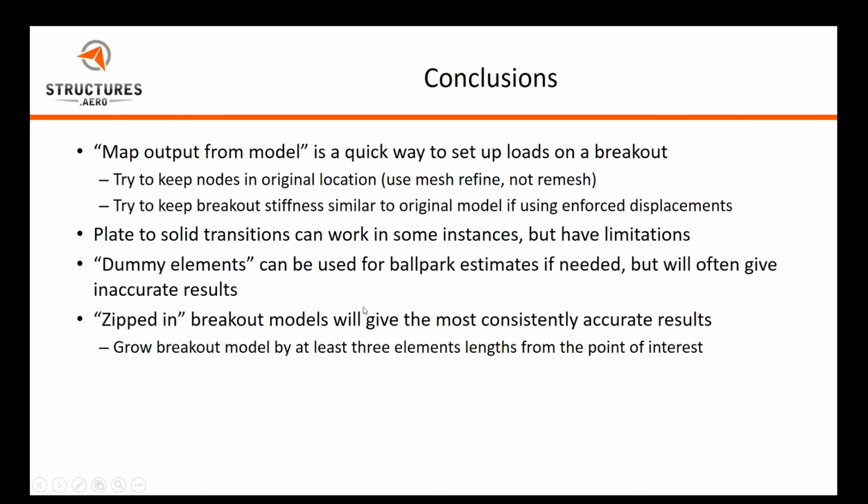So try to keep the breakout stiffness similar to the original model if you're using enforced displacements. There's other options like using forces that I didn't get into in this webinar, but you really just want to try to keep your breakout stiffness similar to your original model. And that doesn't mean you can't make fairly significant changes. It just means you might have to grow your breakout size larger and larger the more you're making changes.